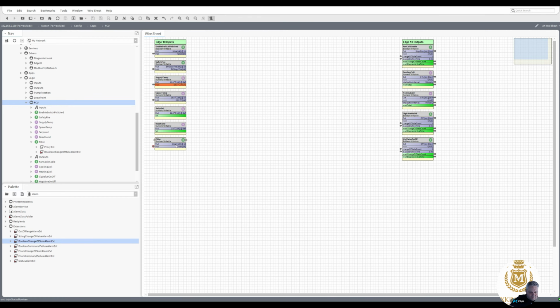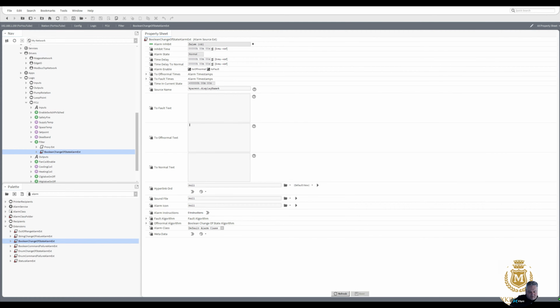So this won't be an alarm now because it's false, but if it ever goes true, it will send out an alarm. And you can actually put in here filter dirty, exclamation mark, and for clean, filter clean.